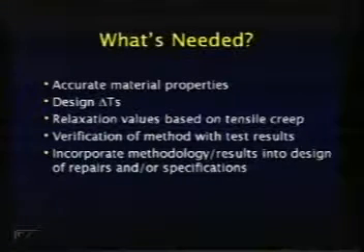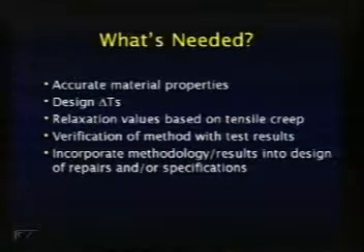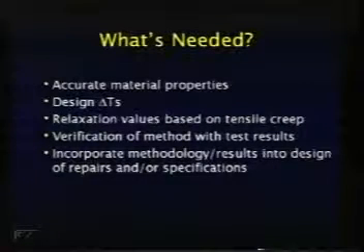We ought to verify the method with test results. And then eventually, if this proves to be an acceptable method, we ought to incorporate the methodology into the design of repairs and our specifications. The same method would apply whether it be a repair or whether it be a large overlay. As long as you're putting down one material over another and you have differences in thermal coefficients, then you could use this procedure.